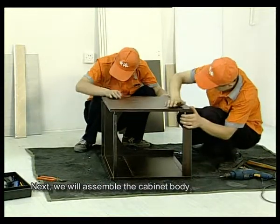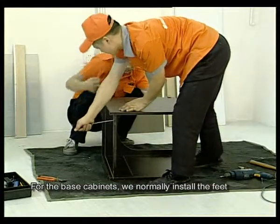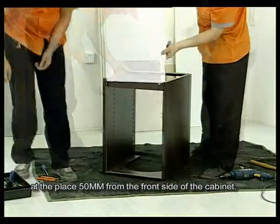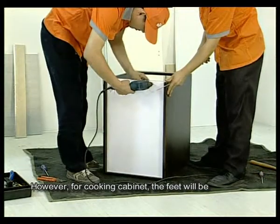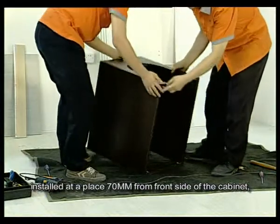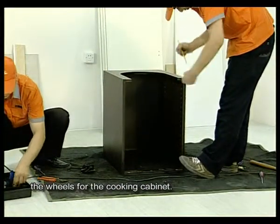Next, we will assemble the cabinet body, the back panel, and the cabinet feet. For the base cabinets, we normally install the feet at a place 50 mm from the front side of the cabinet. However, for the cooking cabinet, the feet will be installed 70 mm from the front side of the cabinet, for the convenience of installing the wheels for the cooking cabinet.